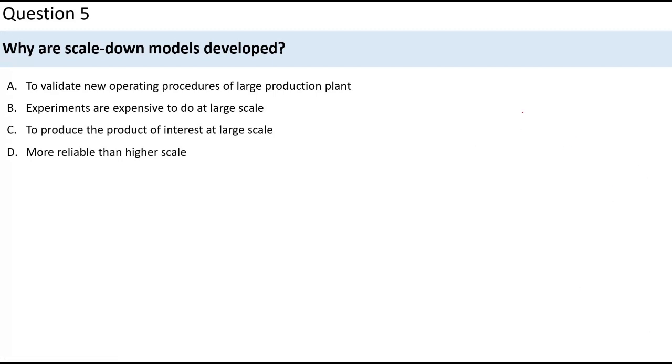So we'll just see at first what scale up is. Usually we do a pre-culture from a single colony or a glycerol stock. From there we inoculate our cells into a 250 ml flask or a 1 liter shake flask. From there we take it up for a lab scale reactor, which can be a 5 liter reactor. So first from pre-culture, I'll be putting it into a 250 ml flask or a 1 liter shake flask, which will be considered as inoculum for the 5 liter reactor.